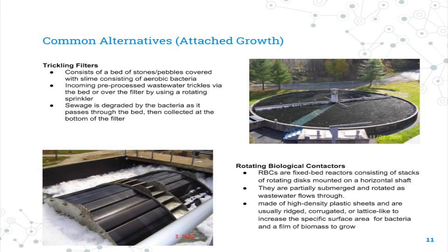For the rotating biological contactors, they are created with a disc design partially submerged, with ridges in order for large amounts of biofilm to attach, which means that there is a large amount of biological mass present to degrade the pollutants. As the biofilm passes through the wastewater when rotating, nutrients and organic pollutants are taken up, efficiently treating the water. The higher contact time in rotating biological contactors due to its rotation allows up to 8 to 10 times higher levels of treatment than in trickling filters.